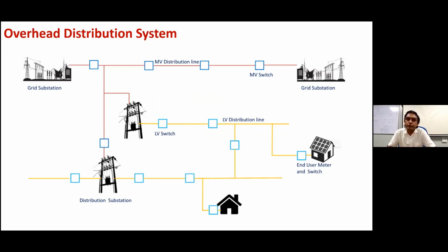Yes, as discussed, Prabath, we know what will happen when the breakdown occurs. Before moving to the automation section, let's have a brief introduction about the typical distribution network in Sri Lanka. Typically in Sri Lanka, other than in Colombo City and Kandy City, all over the area is covered by the overhead distribution network. Considering reliability, the utility's main objective is to run the system in a ring configuration. Though the physical network is connected as a ring, during operation the network is always operated radially by operating section isolators.